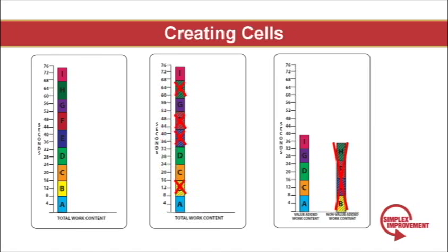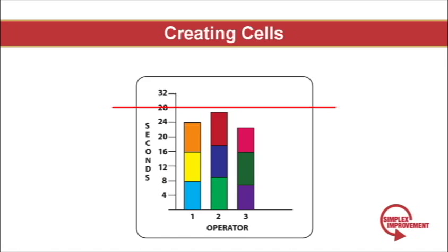Your takt time, your machinery, and your workforce are going to dictate how you divide your total work content. Keep in mind that cycle times at each station have to be less than takt time. Otherwise, you won't meet customer demand. Each worker should understand the work that needs to be completed and the timing in which he needs to complete each task.